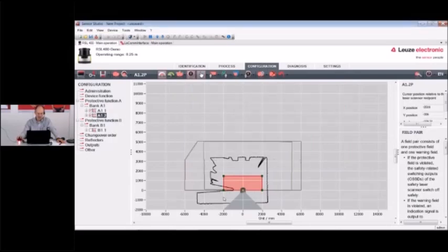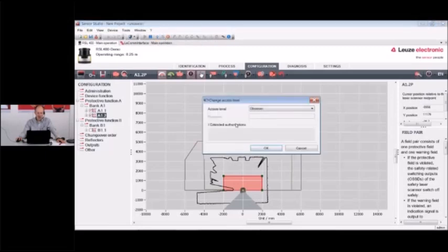Now you see here the online view, what we had before. And now I'm able here with this little arrow to download information. So when I press this, it will now ask me, okay, do you have the access level which is necessary to download information? Everything we did right now, also in the sessions before, was just looking at the scanner, online information, the observer mode. If I would like to edit configuration, I have to go to the engineer mode. And the password for the RSL, also written in the manual, in this case is safety.